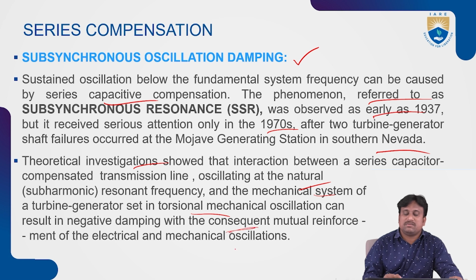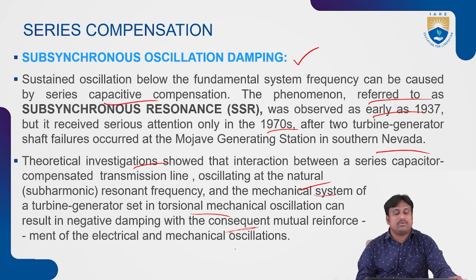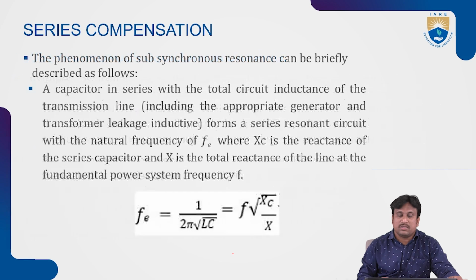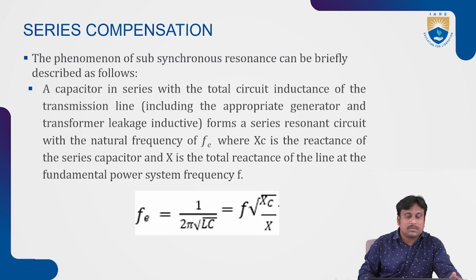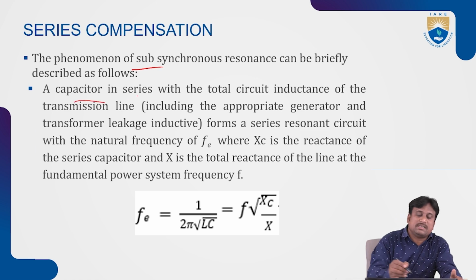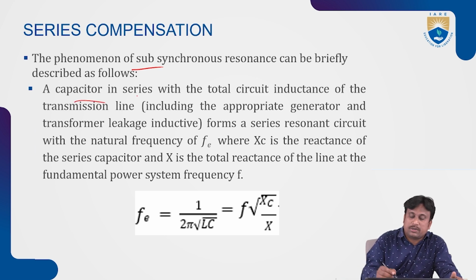This may take place with consequent mutual reinforcement of the electrical and mechanical oscillations. This should have a continuous effect on the whole operating system. So here the phenomenon of subsynchronous resonance can be briefly described through some of its key features. Consider a capacitor in series with the total circuit inductance, L and C.